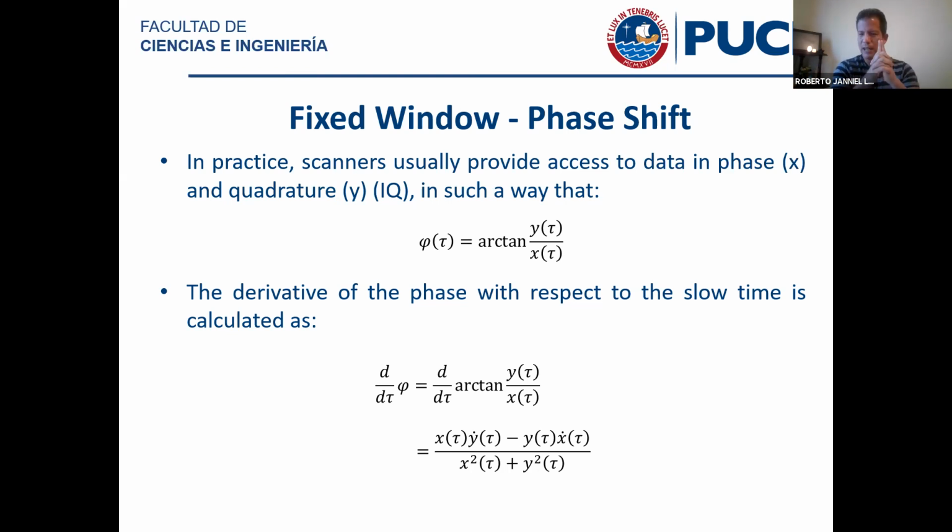When people do that, they create a complex function, because remember, when you bring that component down to baseband, your signal doesn't have a symmetric spectrum anymore. If your signal doesn't have a symmetric spectrum, then your DSP teachers already showed you that the signal has to be complex. So you transform the real signal into a complex signal.